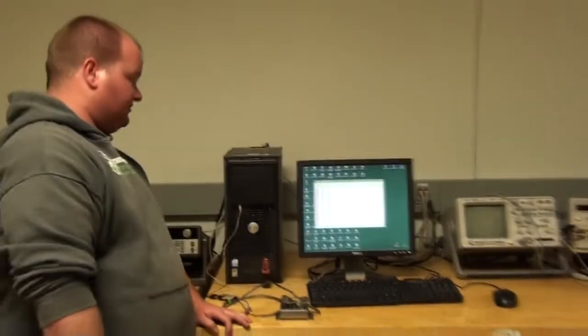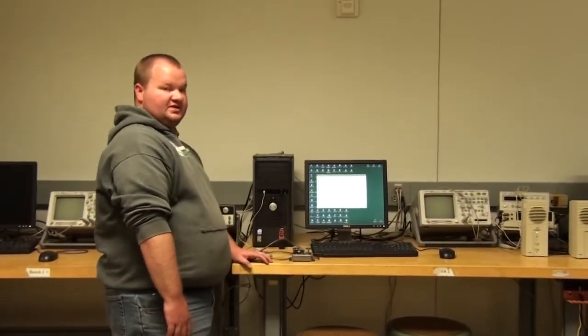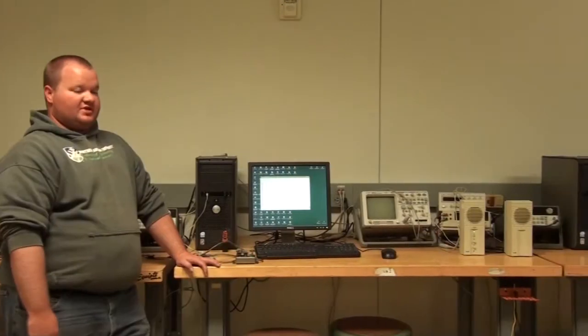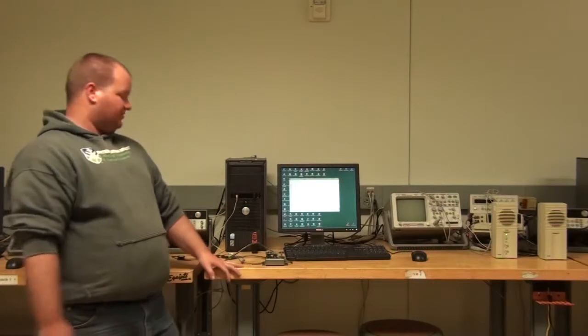Our second column there is going to be our threshold voltage. I don't know if you can see it from the screen or not, but we started out at 1200, because at the top end and the bottom end it gets a little shaky, so we basically have it going in the middle range to get rid of that shakiness. And what you do is you just take the 1200 minus the ADC, and that'll give us our threshold.